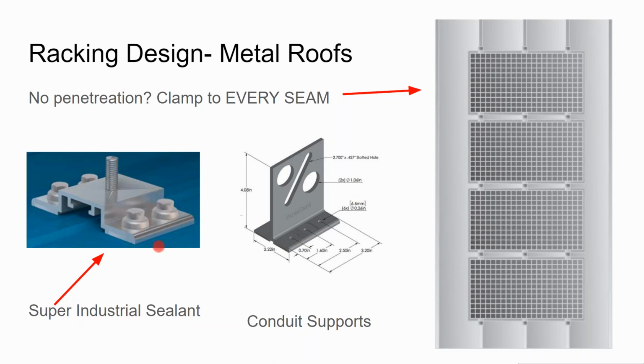the standing seams. On a rolled metal where you don't have a standing seam, you just screw into the purlin or the rafter with a normal metal roofing screw that has a neoprene flashed washer. And the systems have flashing and sealant built into the bottom. You can kind of see it right here. That makes a good connection.